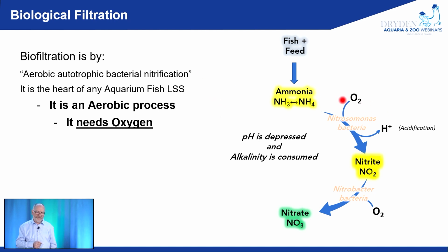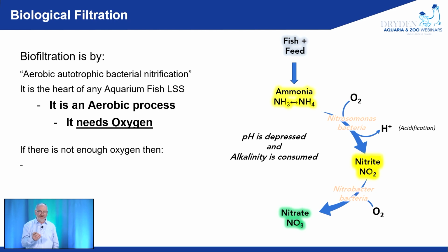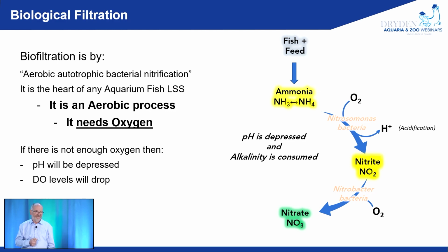The important part is that each of these steps requires oxygen. It is an aerobic process, and it is very oxygen hungry. Unless we keep it fed with oxygen, it cannot be efficient, and we'll get the wrong kind of bacteria developing instead of a managed population of healthy nitrifying bacteria.